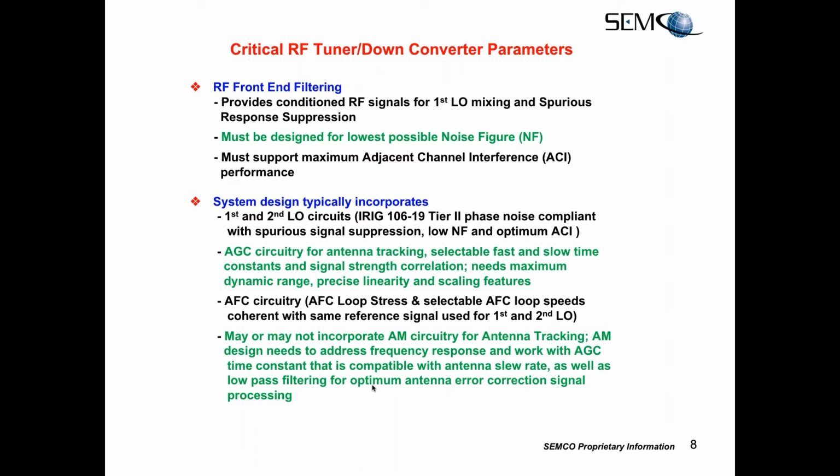And so what is normally done is you want to take a look at, for example, an interfering signal that's at least 30 dBm higher than what we call the victim signal, or the downlink that we are trying to process. So the way a receiver is tested to determine ACI performance is you move that interfering signal in close to the bandpass to see when you see bit error rate degradation in your receiver. And you set the interfering signal at twice the data rate that you're trying to recover in your receiver, and you move that huge plus 30 dBm interfering signal into the bandpass, and then you determine how close you can get and what the rejection is, where you all of a sudden see a 1 dB BER degradation.